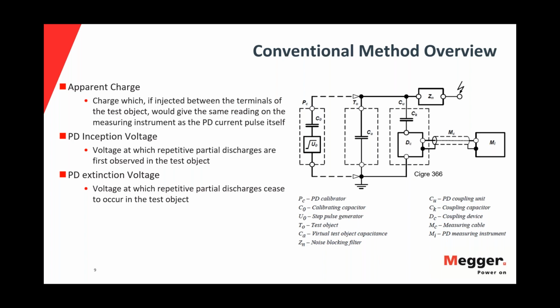In a conventional method, it means that you connect the sensors directly to the output or to your object, and basically you need to realize that localized PD, you cannot measure it directly in the middle of the insulation, but you can measure the result of it, which means that PD will propagate, a high frequency pulse happens in the middle of insulation.